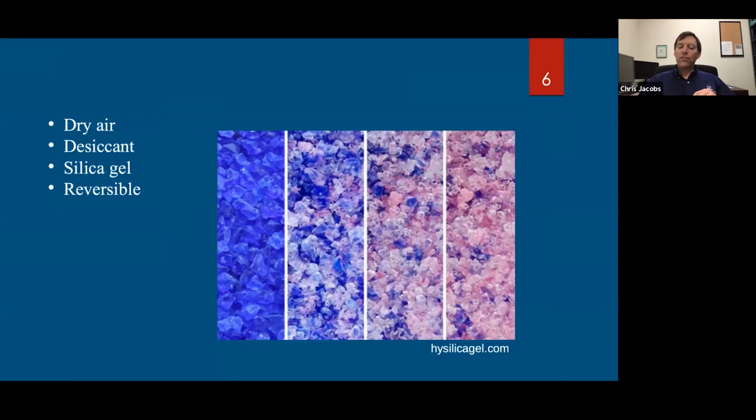And as the moisture is driven back out of the desiccant, it will turn from pink back to this deep blue color. So once the desiccant is all, or 90%, 95% of it, most of it, this deep blue color, it can be placed back in the machine and used again.